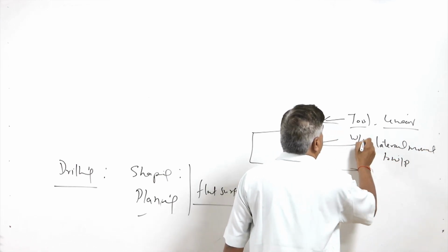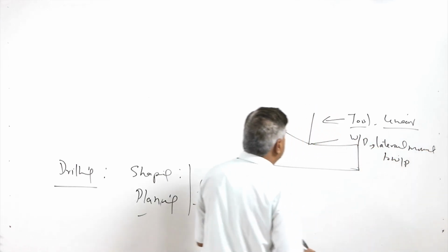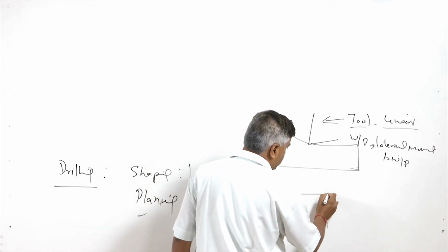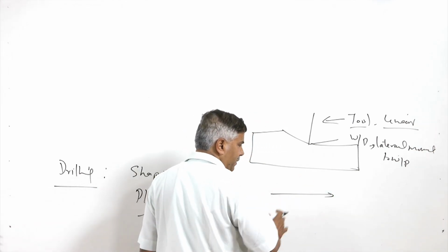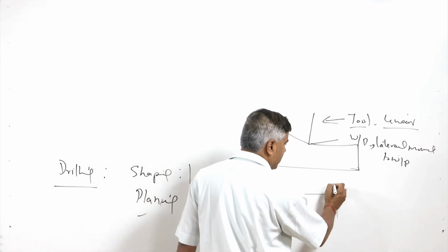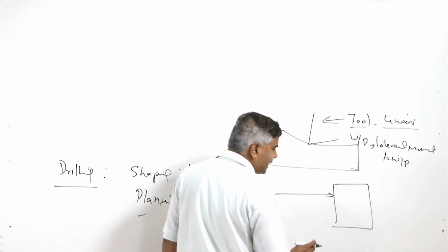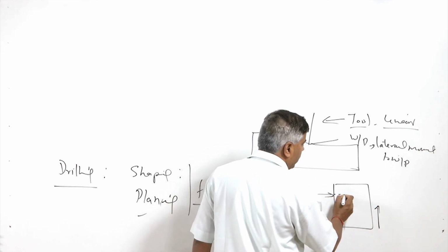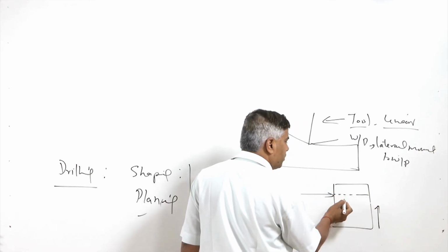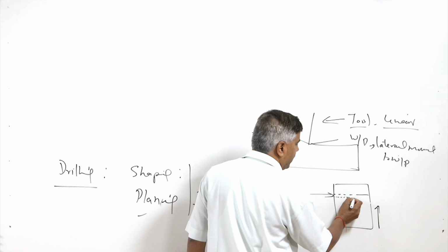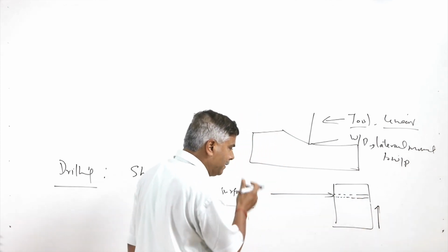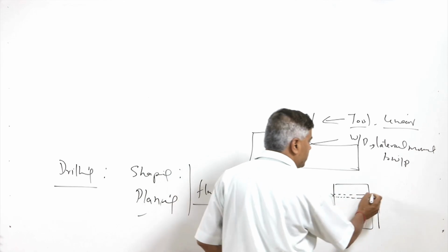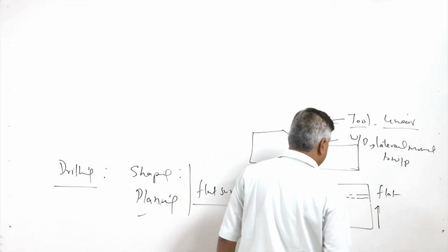The tool is always moved along a particular line for producing the cutting, but in order to cover the entire surface area, the workpiece is moved laterally. So, in one go a cut will be made here, then the workpiece will be moved laterally, and then a cut will be made at another location. These combinations result in flat surfaces.